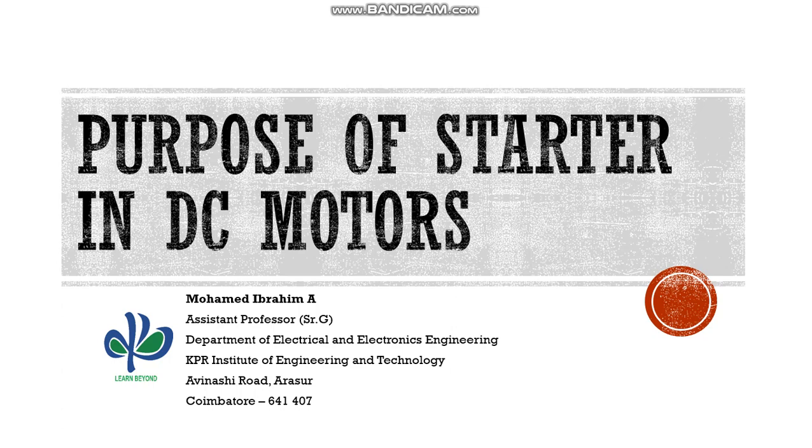In general, starters are used in AC machines as well as in DC machines. As far as machines are concerned, there are two classifications: one is the motor and the other is the generator. We use starters for motors, for AC machines as well as for DC machines. For DC machines, we use 2, 3, and 4 point starters. For AC machines, we use direct online starters, star delta starters, auto transformer starters, etc.